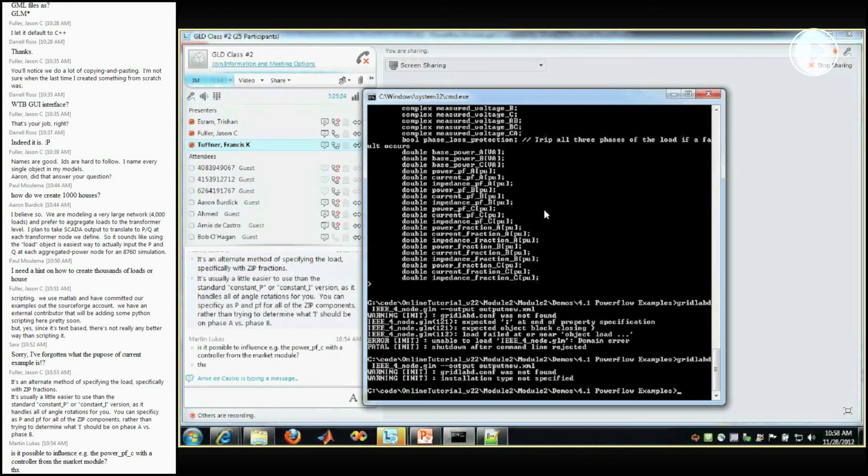And the reason being is because you're doing this time series again. So your initial solution is actually the solution of the previous time step, which is almost always a marginal fraction difference from the last solution. So you're actually always moving from one steady solution to another steady solution. So it's very rare that you would actually get stuck in a local minima like that.